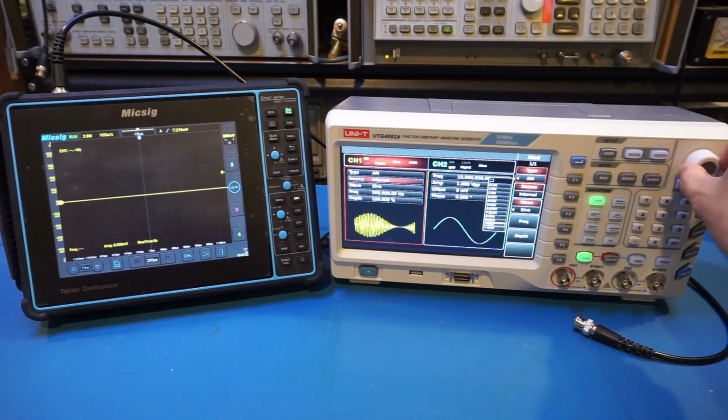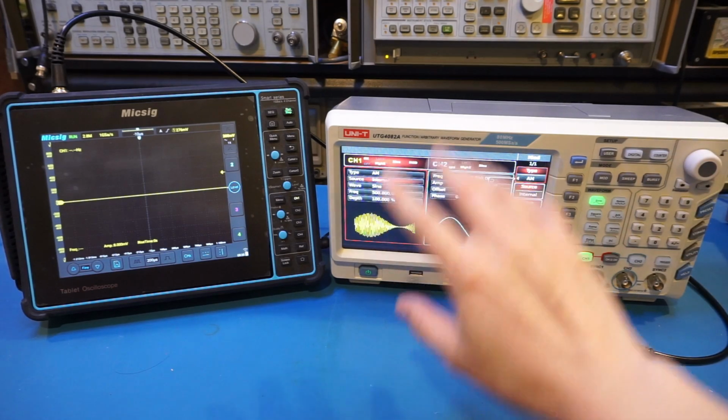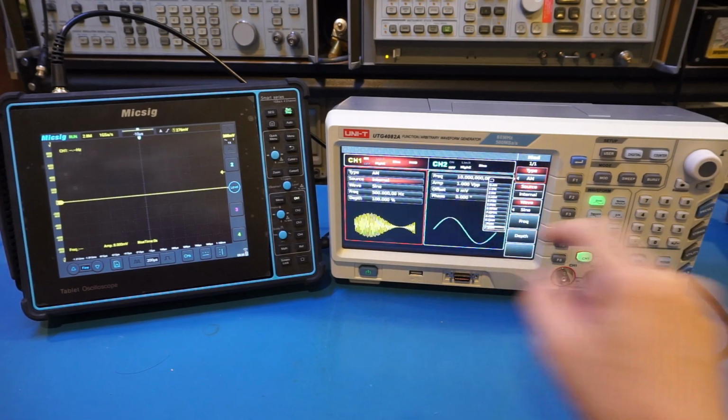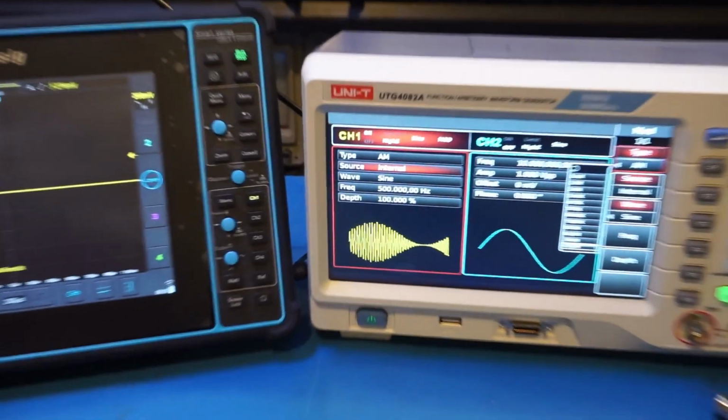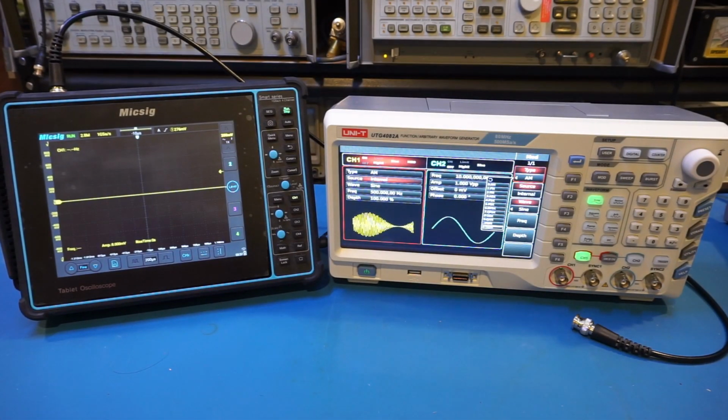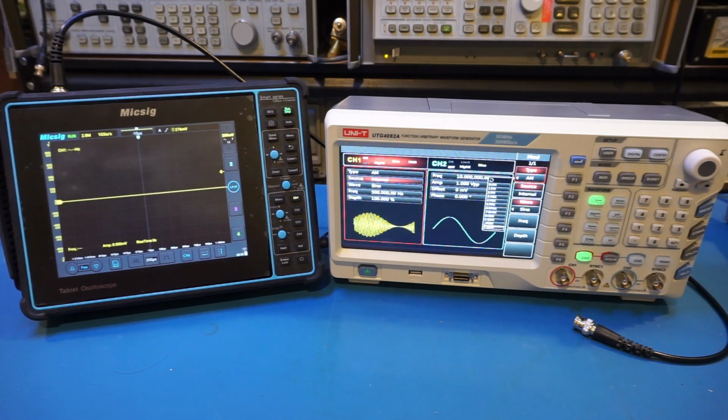Now, one of the very powerful features of this arbitrary waveform generator is it supports sum modulation. You can see here, that's the modulation type. And sum modulation is very powerful because you can modulate an arbitrary waveform with another arbitrary waveform. Although a more typical use of sum modulation is to modulate a percentage of Gaussian noise onto the carrier waveform. Anyway, let me do a quick demonstration here.